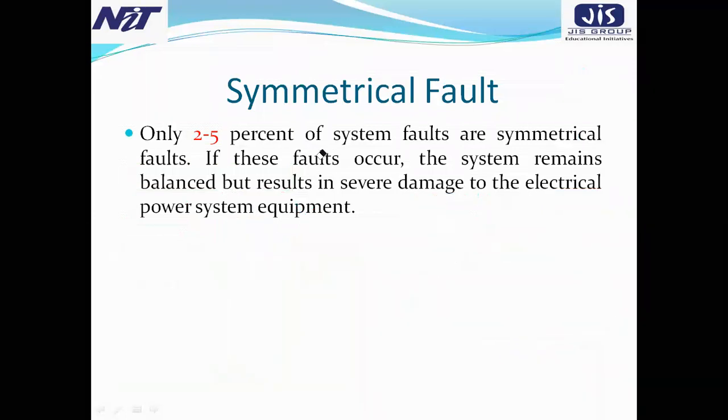So for that reason, you will find only 2 to 5% of system faults are symmetrical faults. Only 2 to 5%. Just remember this. If these faults occur, the system remains balanced but results in severe damage. This is the dangerous part for the electrical power system equipment.